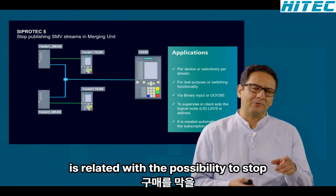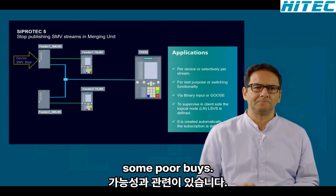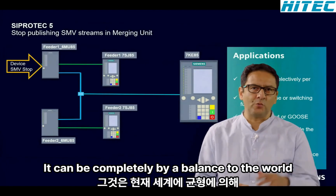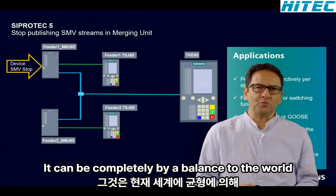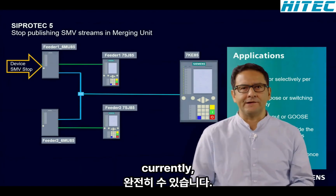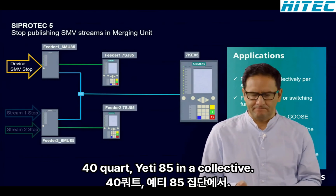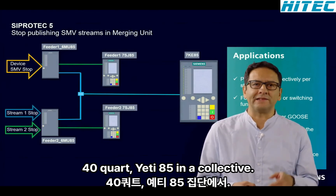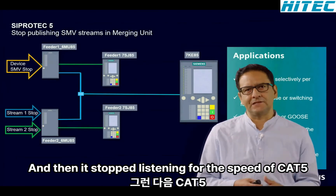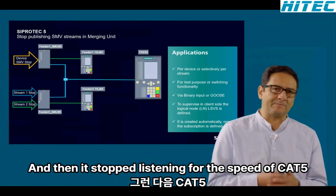Another mechanism available in SIPROTEC 5 is related with the possibility to stop sample values. It can be done for the complete device, as I am showing here in the slide. The merging unit 1 will stop publishing sample values to the feeder protection relay that I'm having here, and to the fault recorder, 7KE85. Or it can be done per stream, where it's possible in a selective way to stop first the stream for the fault recorder, 7KE85, and then stop the stream for the feeder protection 7SL85.